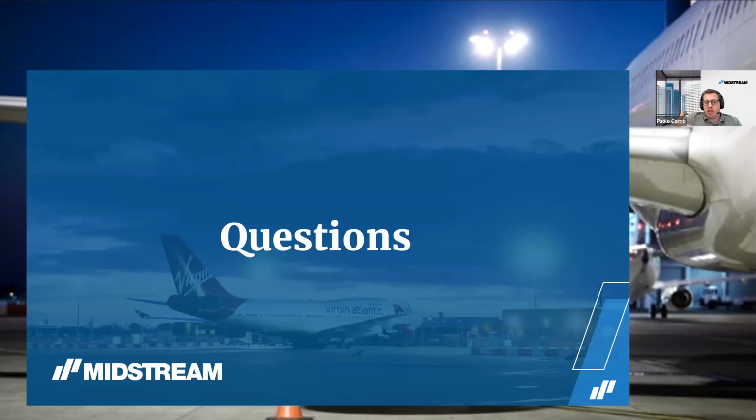That is the minimum you need to evaluate if you actually have a good uniformity or not. It might be enough to show compliance. That depends on the Civil Aviation Authority requirements. But from a practical point of view, 25 points is the bare minimum you need to make sure that you have a decent uniformity. And for the way you place the points, we're going to refer you to our guide on the website, because it's a bit lengthier process.